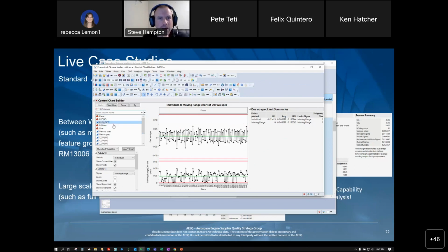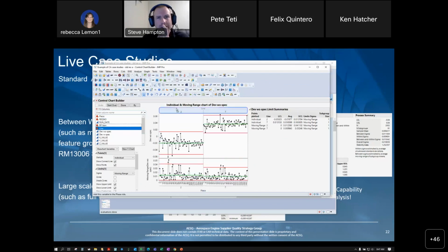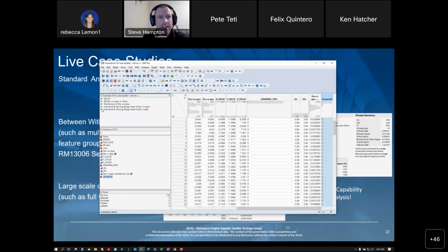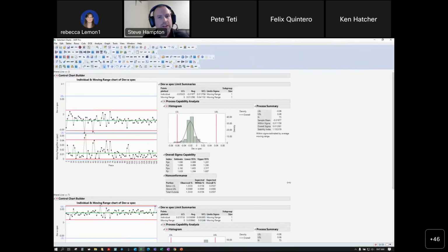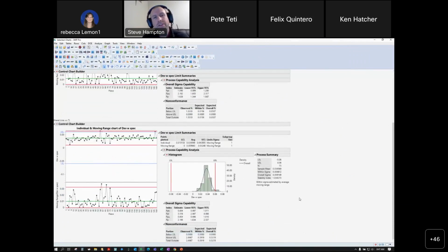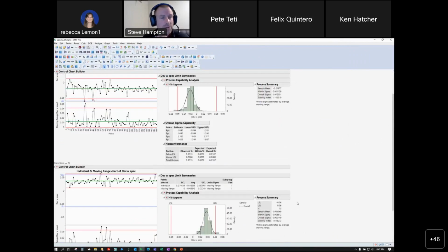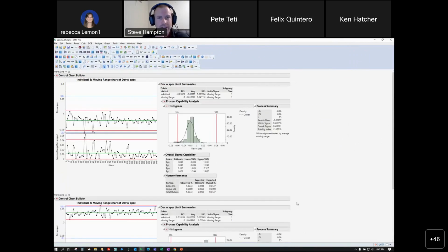And what's going on? I'm going to put my process hat on, dig into this a little bit more, and drag this over. Holy smokes. It's because I have such different outputs from my line 2 versus my line 7. So I actually now split up the data and look at it. I actually have 2 normal distribution capability analyses I could do. And I have a very nice process improvement project I can take on to see why my 2 lines are not behaving like they should be.